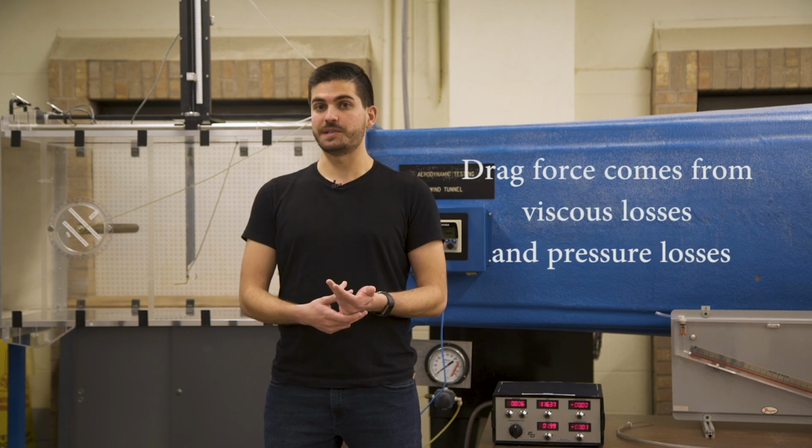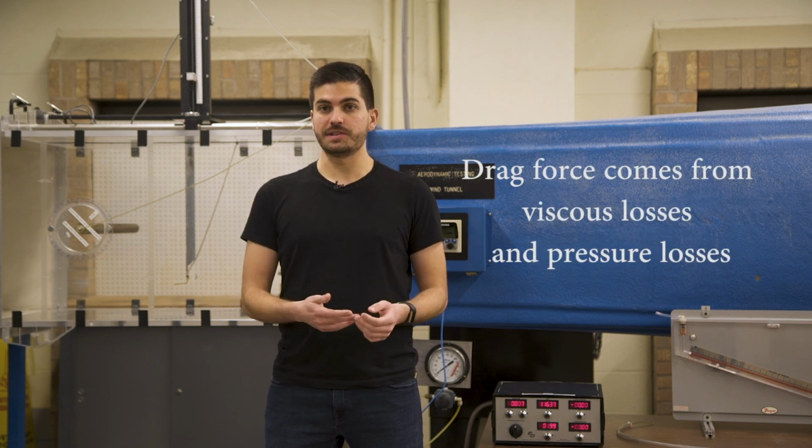So once again, today we're looking at a cylinder in cross flow. This is a pretty classic fluid dynamics problem that we can learn a lot from. We'll be focusing on the drag force on this cylinder, and in fluid dynamics, drag comes from two different sources. At low Reynolds numbers, viscous forces dominate, but in our experiment, we have a high Reynolds number, so pressure forces